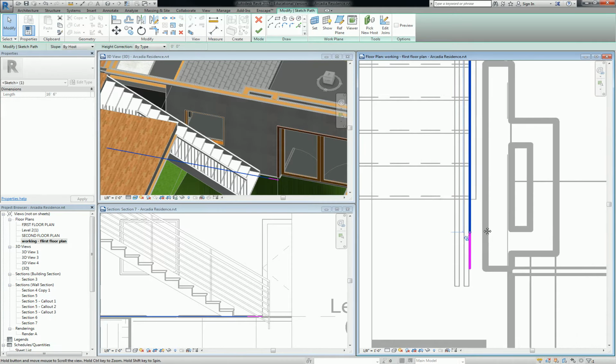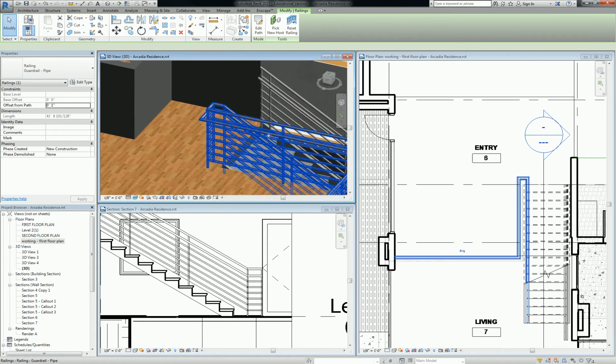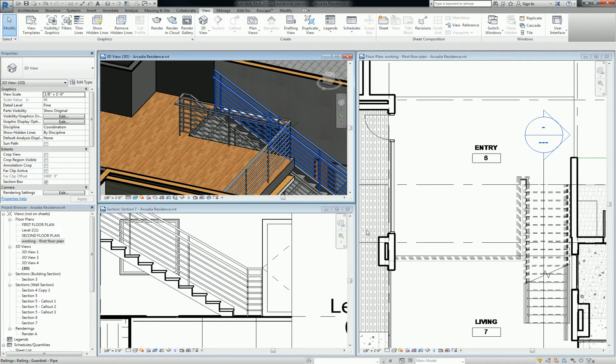Okay. So what I need to do is stop this, and then start a new line segment, have that go 6 inches out. This one will probably go 6 inches as well. And then this line segment will continue all the way around here. Does that make sense? Yeah. So we actually got it to sort of behave like that, and the lucky thing for us is that this is a really simple handrail, so we somewhat emulated this condition.